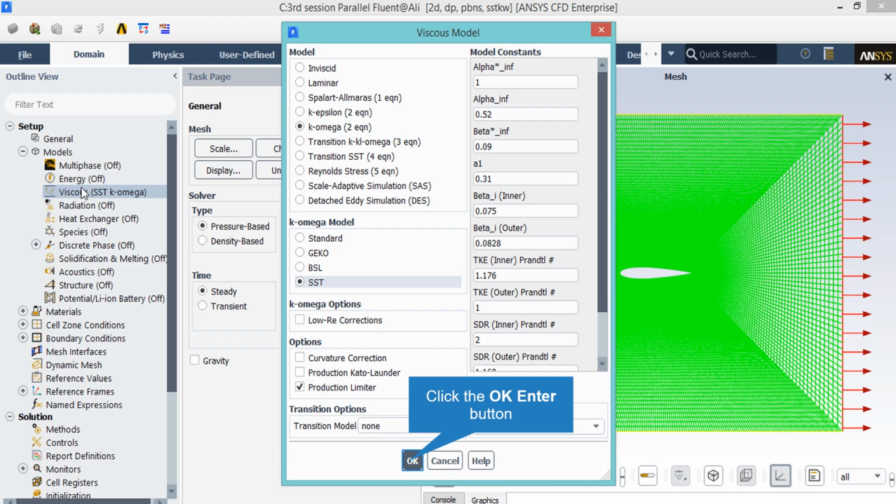In this project, we are going to use the turbulent models for solving our fluid flow. Among the existing models, for the normal systems that we have, it is more common to use K epsilon and K omega models. There are a lot of differences between these two, but the most important difference between them is how they model the velocity profile in the boundary layer.